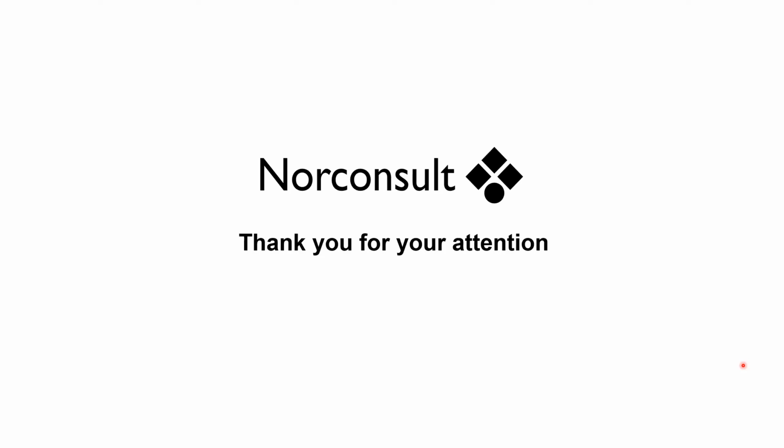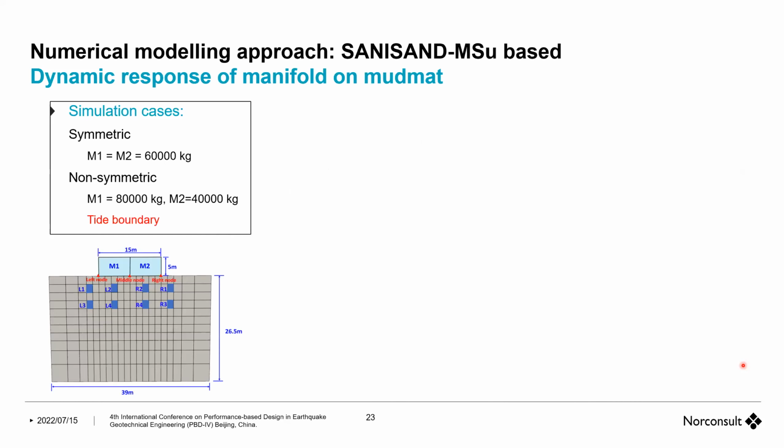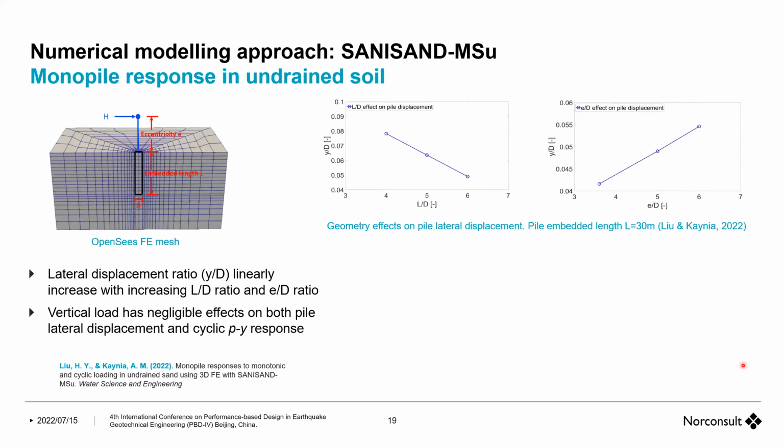Probably you would see the same thing even without the more advanced MSU version, even with the 2004 one. However, you have to come to large strains so that it has this new feature of the response. Maybe I didn't see very well the whole range, because I thought you showed it for the entire range. No, it was not, but of course the low range maybe is not of much concern. The concern with the lower range is when you have a deep deposit and you have to propagate through lower strains to higher strains, and then it can overdamp.